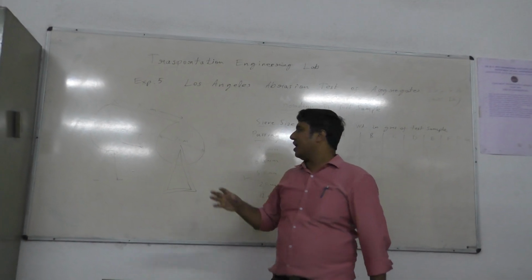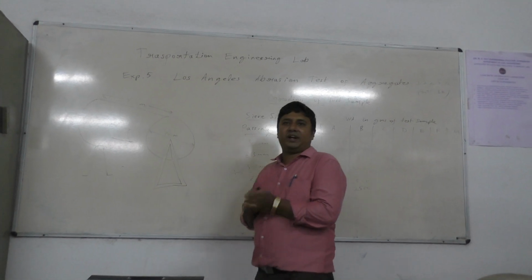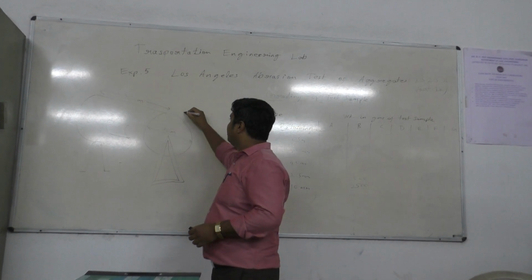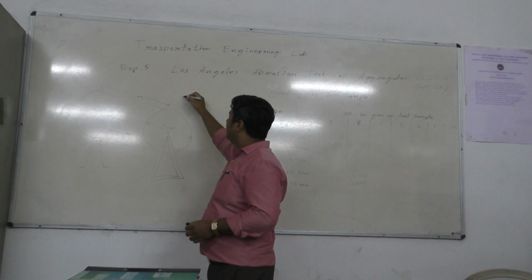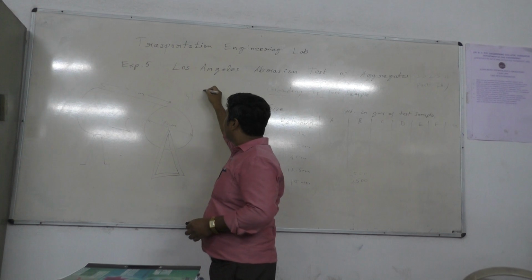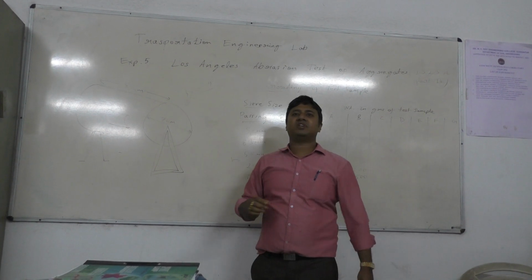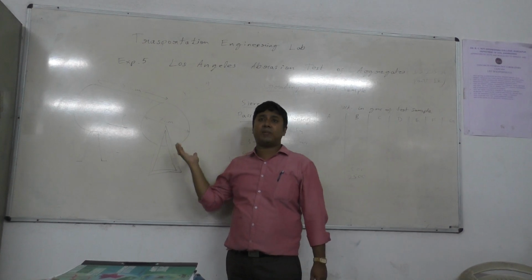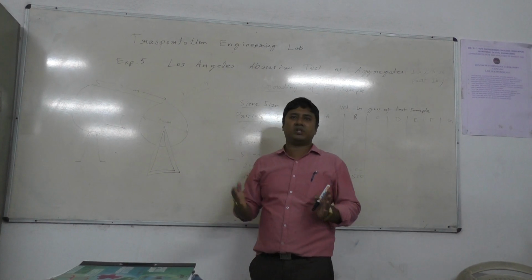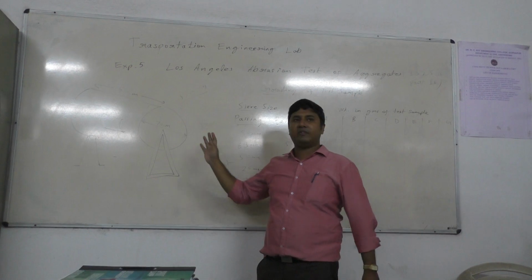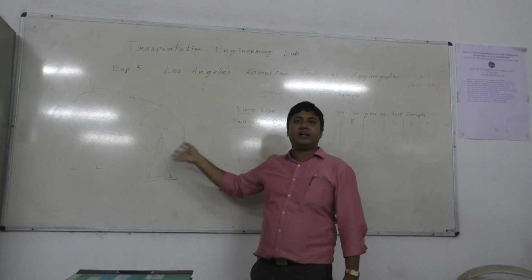We will fill it and this drum will be rotated uniformly at around 33 RPM, for a number of revolutions, around 500 to 1000, based on the grades that I will discuss. So based on the grade, it will be rotated.